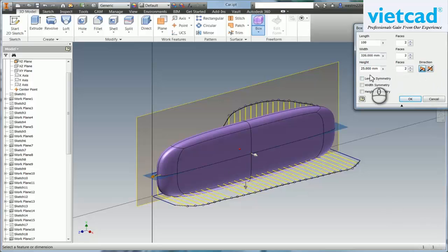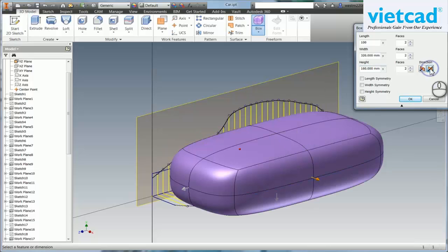Like I said, we're going to be doing the whole car and splitting it at the end to give us that really the freeform model and get the aerodynamics out of it. So here I noticed one of the sketches was about 80mm long, so if I make that 160, and what we're going to do is we're going to make that mid-plane.